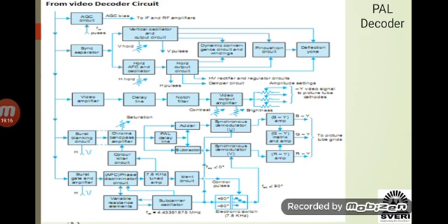So it's nothing like NTSC is better or PAL is better, but after NTSC had been studied and launched, the PAL system came in its early days. So PAL has taken over that. If an error has occurred in case of NTSC, that phase shift error can be eliminated in case of the PAL system, and that has been used in Germany as well as in the Indian subcontinent, or like in the Asian subcontinent.